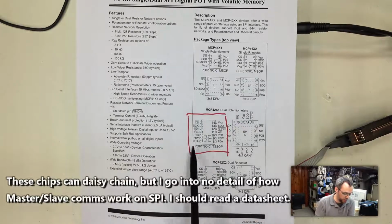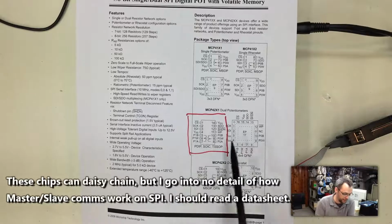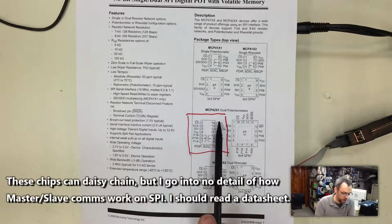Allowing you to use fewer traces on the board instead of connecting all the clock and data lines for all of the chips together. You can just chain the data out onto the data in, saves a little bit on board trace, a little bit on board complexity, and then when you want to talk to any chips farther in the chain,